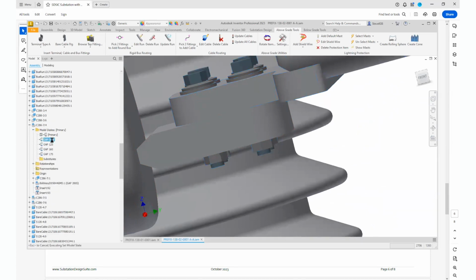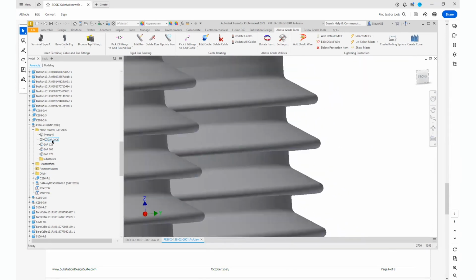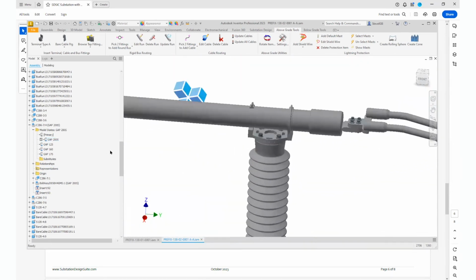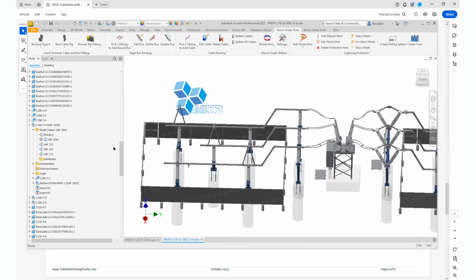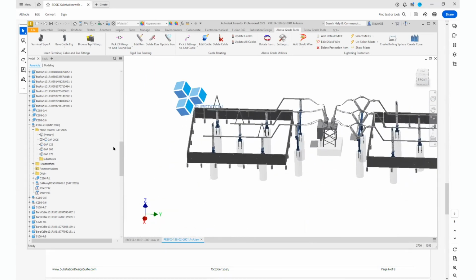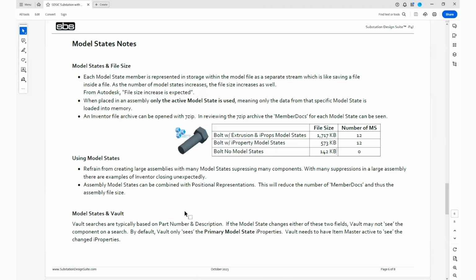Do I want 2 inches? Do I want 1.25? You can see it disappearing there. Do I want 160? Do I want 175? All right. So you're able to move it around like that. I don't know why I don't have the size. This must be it. All right. You can see that we're moving that around. And so I'm making that as a sub-assembly. So now I'm able to place these fittings with the bolting on, adjust the bolting right away, and I'm done. I'm hunky-dory type of thing.